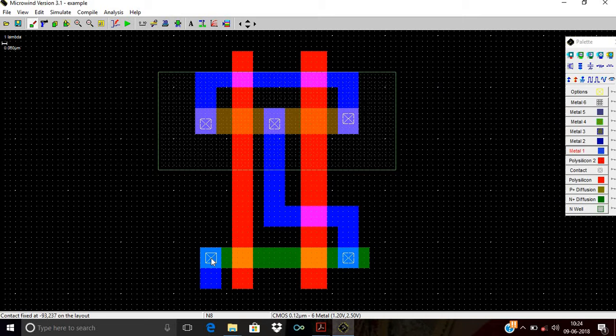Okay, now everything is completed. Source is connected to the ground. This source and this drain are shorted, and from the drain we have taken the output. The drain of both P channel MOSFETs is connected to the drain of the first. Now connect VDD and supply. VDD you have to connect here. Both sources are connected to VDD.